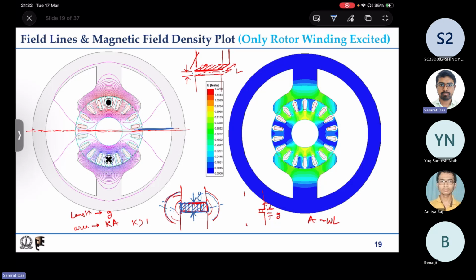It gets difficult to calculate reluctance directly, or reluctance is an approximation. In the first few lectures probably I have discussed, reluctance is a magnetic circuit concept. So actual magnetic field can be approximated as a magnetic circuit for a few cases where most of the flux path is through iron and only a small portion is through the gap.